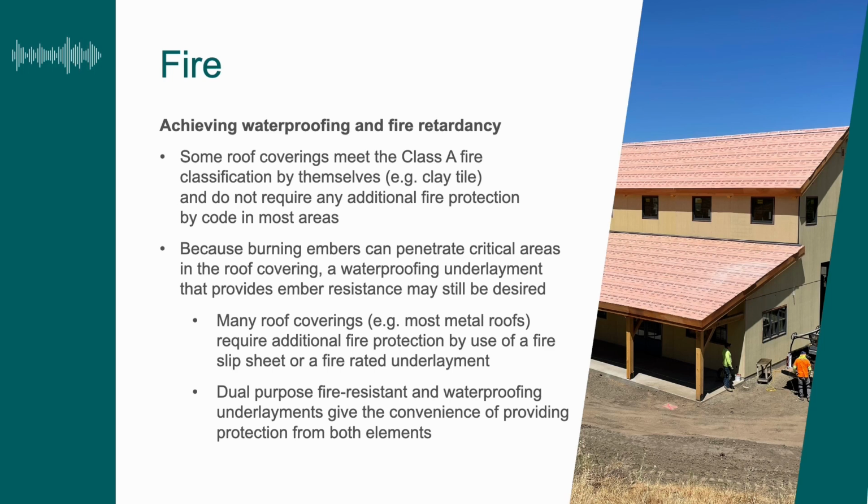If you've never seen a video of a UL 790 fire test, the burning brand especially is pretty severe. You've got a big 2-foot by 2-foot, 3-layer hardwood that's being lit on fire and set right on top of the deck, and then a 12-mile-an-hour wind is blown at it on and off for 20 minutes. In the second part of the test, you set it on there until it completely burns away. That's pretty severe for a roof covering.